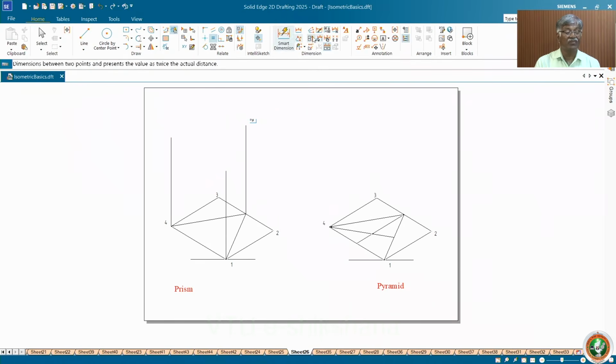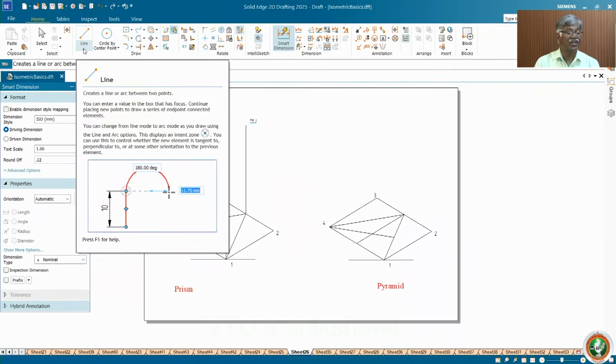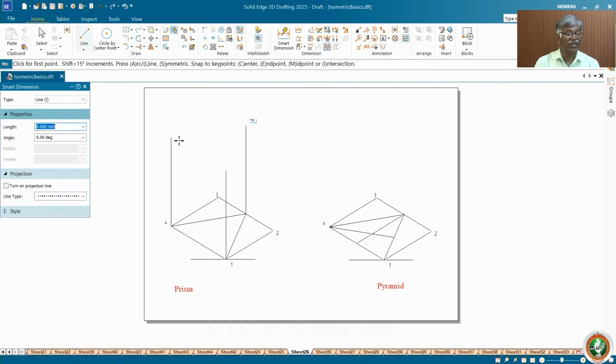Now you measure for validation, see, 80, 80. After confirmation, you need not confirm all the time. At the beginning you have to do this job. Now join them. Join all this. Now what happened? Top face is ready, base is ready. Now visibility. Now darken all the top face edges. Select all top face edges.